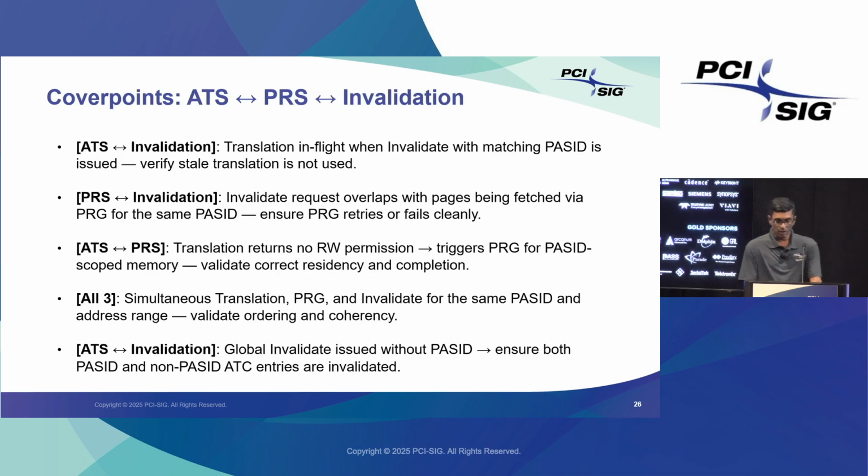Cover points, if you want to see initially, how many constraints are hit will at least tell how many scenarios we have already hit. We can even write cover points to understand whether those scenarios really came in the monitor or not. But I think for the time factor, I use constraints to cover whether all complex scenarios are hit or not.